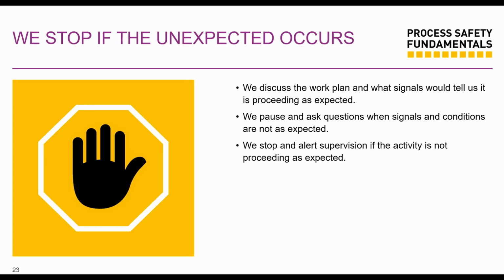You're doing your walkarounds or your rounds in a facility that has a lot of H2S, and you hear an H2S alarm, or you're carrying out an activity and you hear an H2S alarm that's not related to your activity. Maybe you need to stop and say, hey, where's this H2S alarm coming from? Maybe I need to get out of here. Don't get so comfortable walking through these conditions that are not normal, or operations identify a pinhole leak.